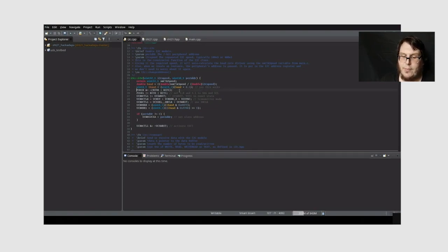It'll take care of calculating those baud rate registers for us. Then, as you can see, we make sure that the... I'm not actually sure why I have this line in here, but we set the direction to be inputs for some reason. Then we set those two bits, bit 0 and bit 1, to be SDA and SCL like we saw earlier. We set the I2C peripheral into reset. Remember, this is that really important step. Before we can change any of these registers, it needs to be in reset. Just like the example code I showed on the slide, we set the UCMST bit, UCMODE 3, which is I2C, UCSYNC. In the control 1 register, we select SMCLK, and we make sure that the software reset is still set.